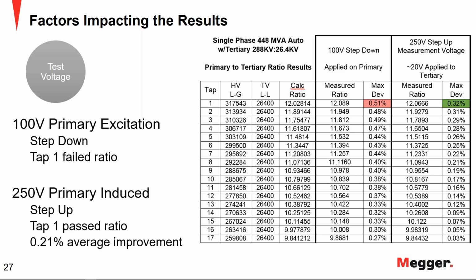This brings me into my next discussion because if you will note in the top right-hand corner here, there's 250 volts step-up measurement voltage, but 20 volts was applied on the tertiary, and this is what we refer to as the step-up method of testing.